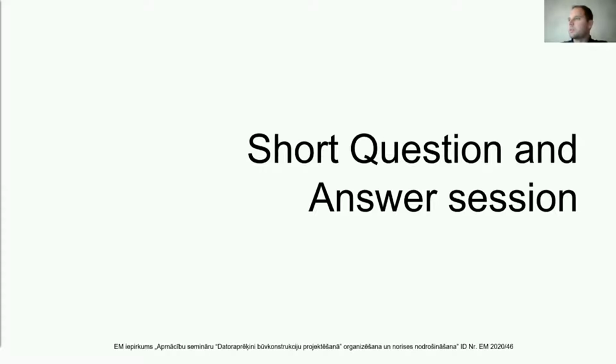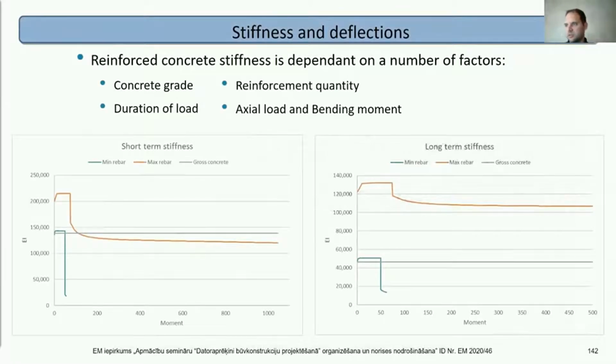slides about how should we, in finite elements, model the cracking of concrete, and should we take into account this stiffness change or just ignore it? What is your recommendation? So obviously the first model you're looking at, your initial model, you want to work out what the reinforcement should be. And so you're looking purely at bending moments and shear forces.